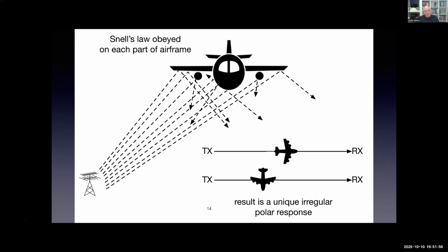The engines, the fuselage, the wings, and we get a very different reflection pattern if we paint an aircraft that is traveling down the path in the top example, compared to the aircraft traveling across the path. You can imagine that the reflection going down the path is going to be a lot about reflection from the wings, whereas going across the path is going to be a lot about reflection from perhaps the fuselage, and a lot of the wing reflection is actually blocked by that fuselage.